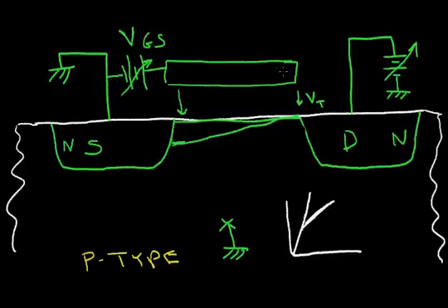So this is going to be higher voltage relative to the drain by the threshold. So I'll just be starting to form the channel at the drain terminal, but at the source the channel is quite deep. Now, under this condition, I'm reaching a point where this device starts to behave as a constant current source as I raise my drain voltage further.